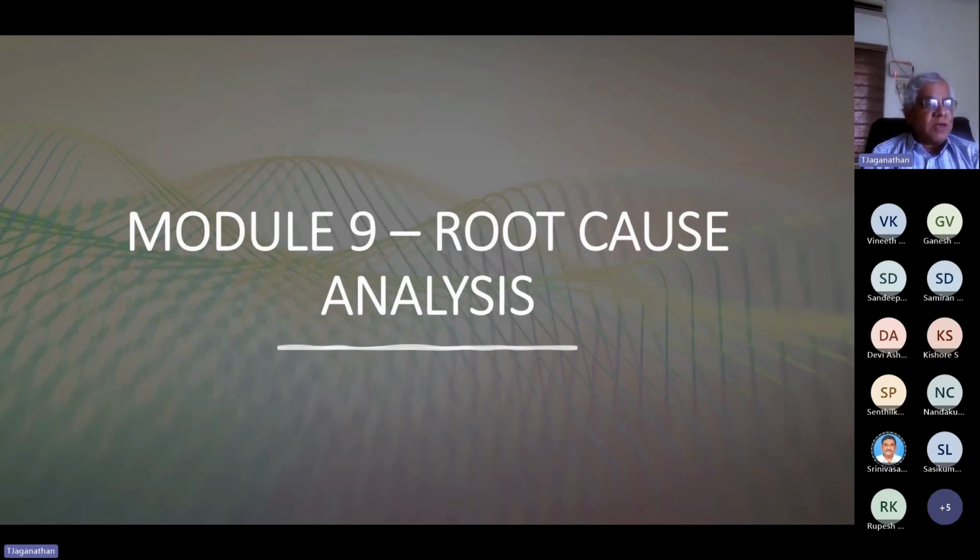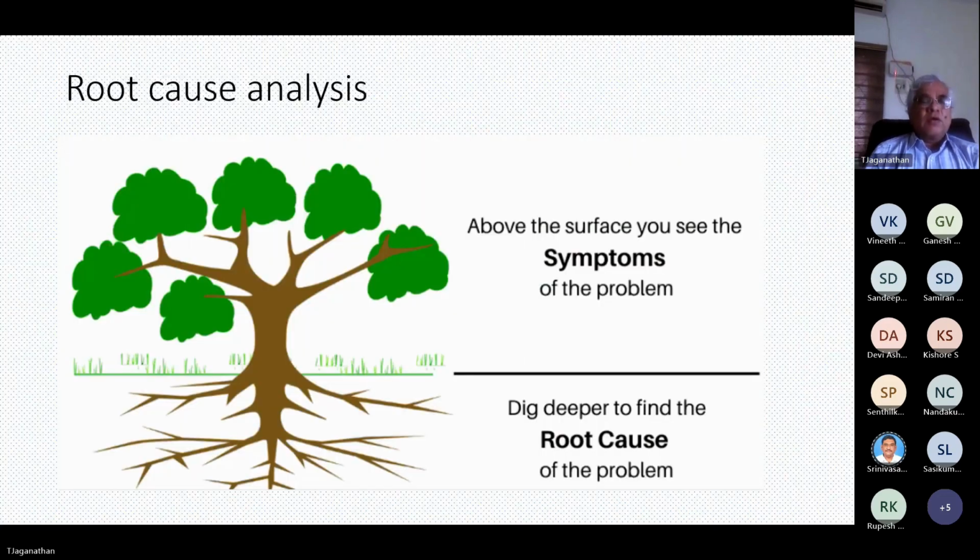The idea is that only if you understand the root cause, it can be completely removed. Otherwise, it will only be incidentally removed. It will keep recurring. Okay, what is the root cause analysis? A little bit more detail. What you see from any non-conformity is only a symptom of the problem. But there may be certain things which are not visible to you, so you have to dig deeper to find the root cause.